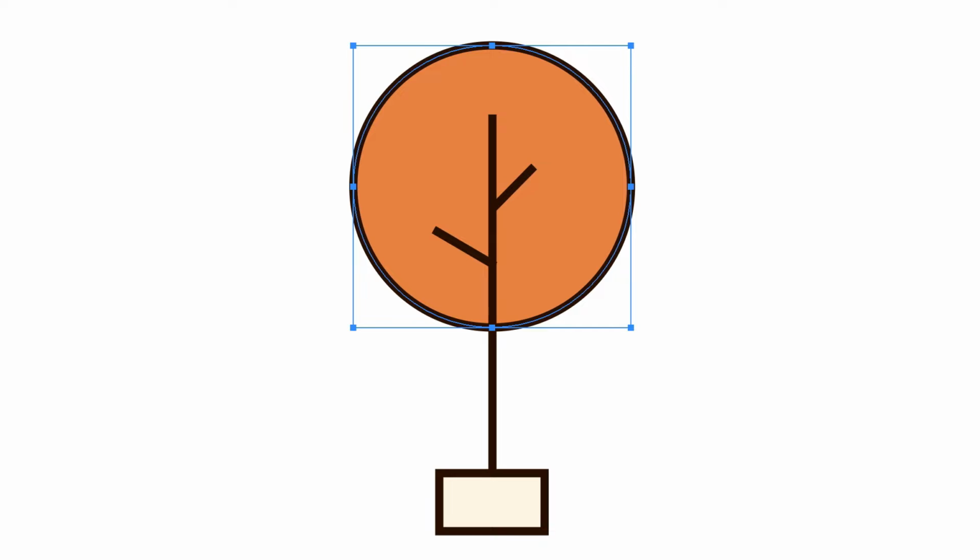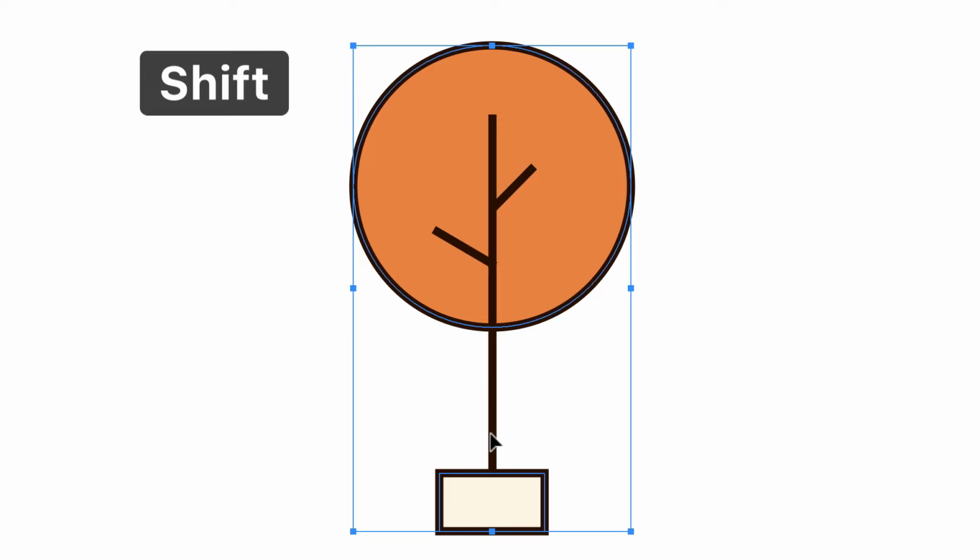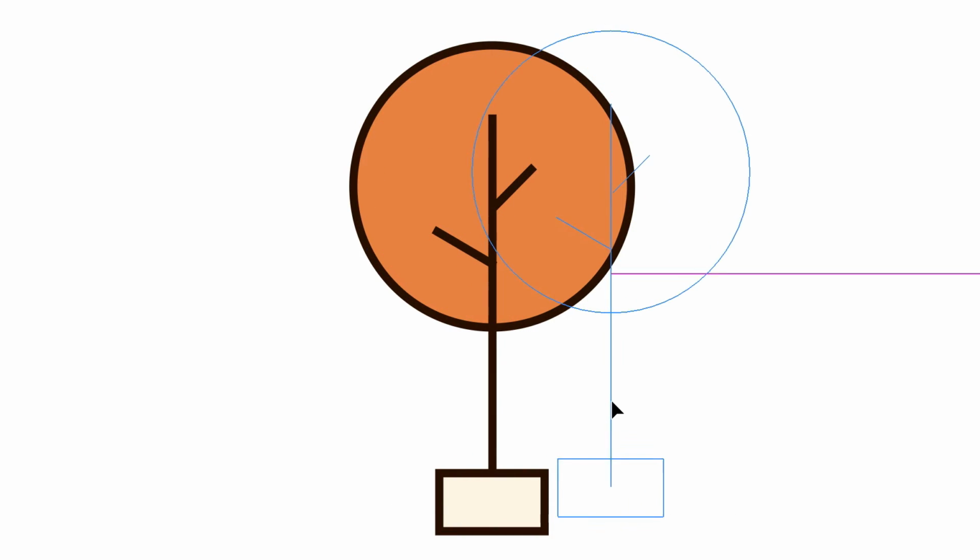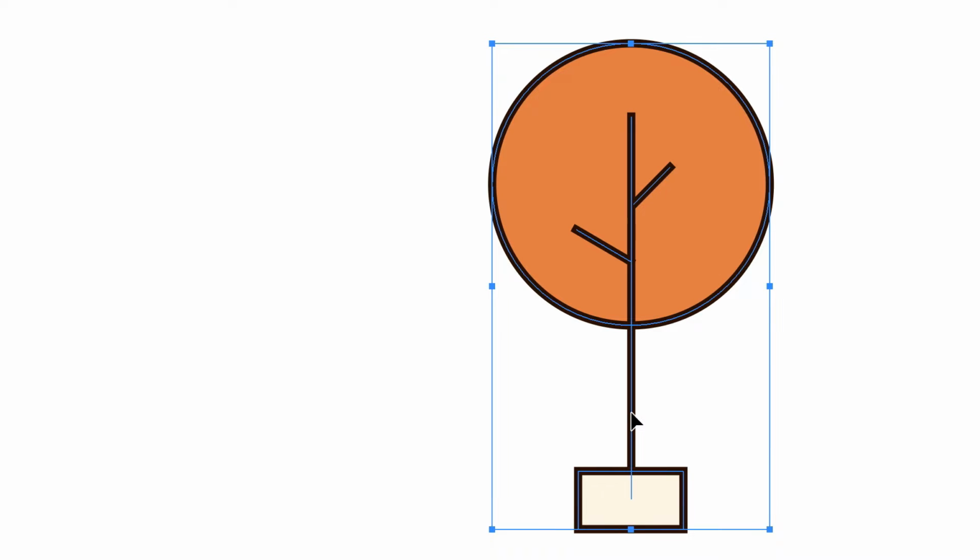The next step is to select the items on the canvas which we want to modify. Click once if you want to select a single shape or path. Hold the Shift key and click on several items if you want to make a multiple selection. Several selected shapes can be moved simultaneously, but if you want to deselect any of them, click on it again holding the Shift key.